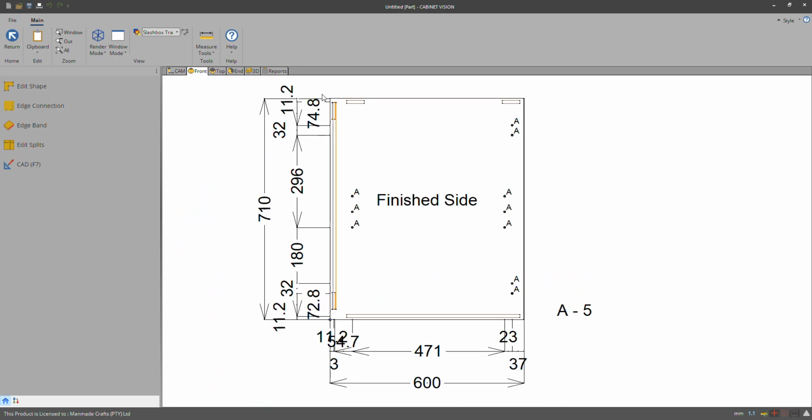So you're cutting like an L? No, if you have, let's take this one for instance, it's basically a mortise and tenon. If you want to connect this like that, here it'll cut that off, leaving you a little lip there. Let's say it's 8 mil deep and that little lip is 8 mil wide. Then it'll cut you a little 8 mil slot there that just slots into it.